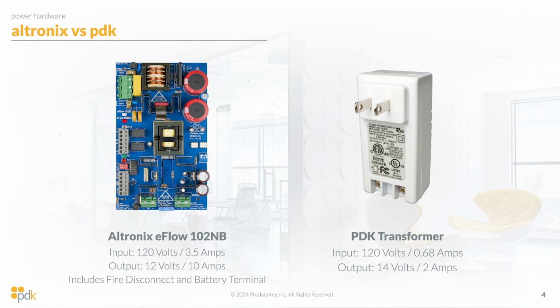So you can see right there, the input is 120 volts, about 3.5 amps, and the output is 12 volts and 10 amps. So you can see it's just transforming a high voltage down into a usable low voltage for PDK. So that 12 volts and 10 amps means we have, with an 8-door controller, a little over an amp of power per port. Now additionally, these eFlow boards have a built-in fire disconnect and battery terminal, which you can find the schematics for in their documentation.